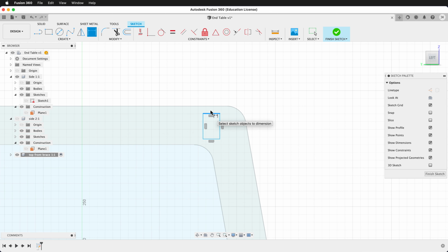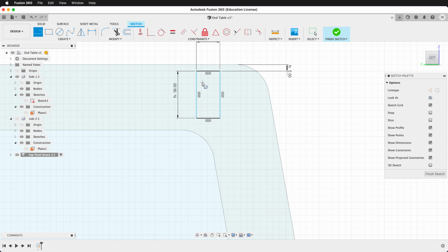The dimensions of this rectangle will be ply. The height of it will be brace. The dimension from the top will be gap. And then we need to draw 2 more lines. So we'll draw a line horizontal here and a line horizontal here. These 2 lines will have a dimension of ply. And this space right here will have a dimension of brace minus ply divided by 2.